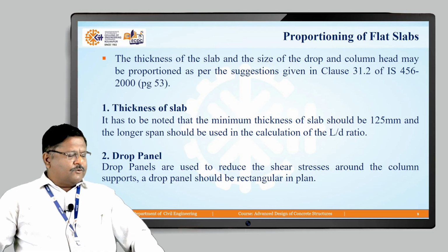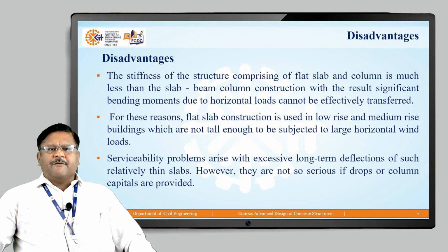And third is the serviceability problem, which arises with excessive long term deflection of such relatively thick slabs. However, it is not so serious if drops or column caps or column heads are provided. Means the thickness of the slab cannot serve for a long time, but if you provide drops and column heads, it is not that serious a problem in the design or in the serviceability.